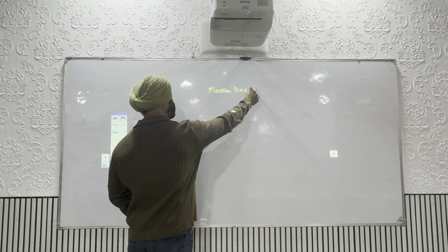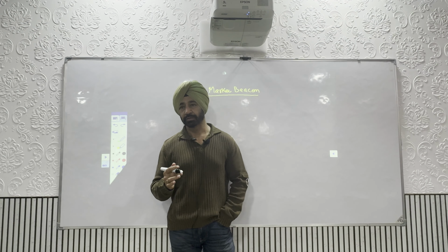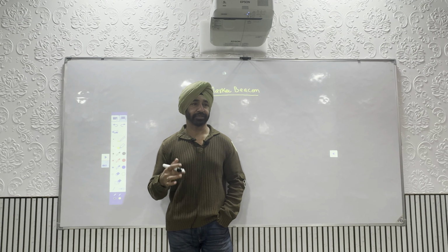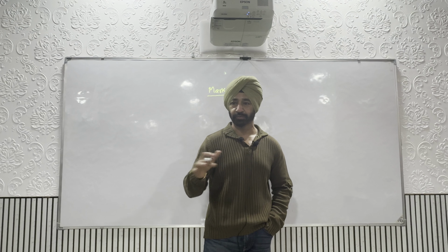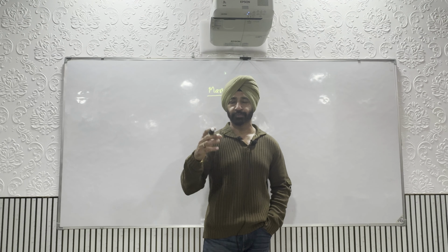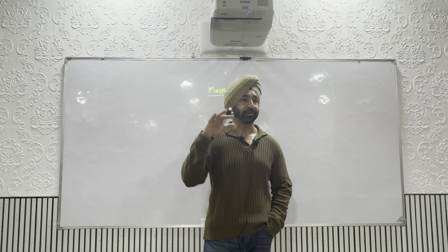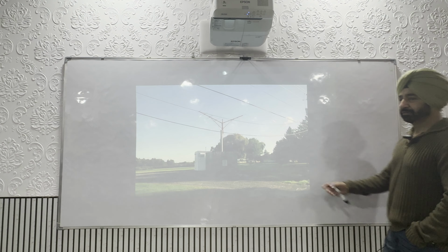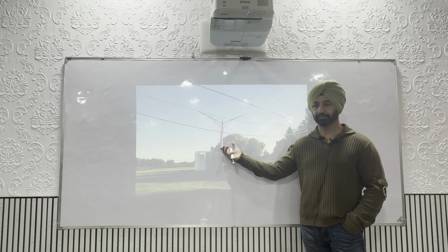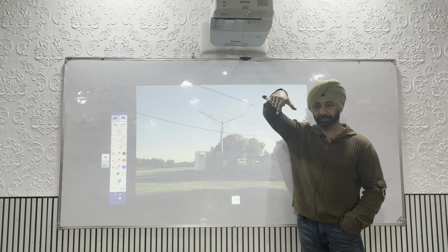Now, over a period of time, this is the only component which is replaced with DME, distance measuring equipment. When this was invented way back in the 1930s, technology was very primitive, or the advancement was not what came later on. So at that time, to know the decision point, they came up with a simple solution: transmit vertically up. When the aircraft is above that, it will receive the signal. You saw that antenna, how it looks. This is a marker beacon antenna, which transmits vertically up. So only when the aircraft is over that, it receives the signal.